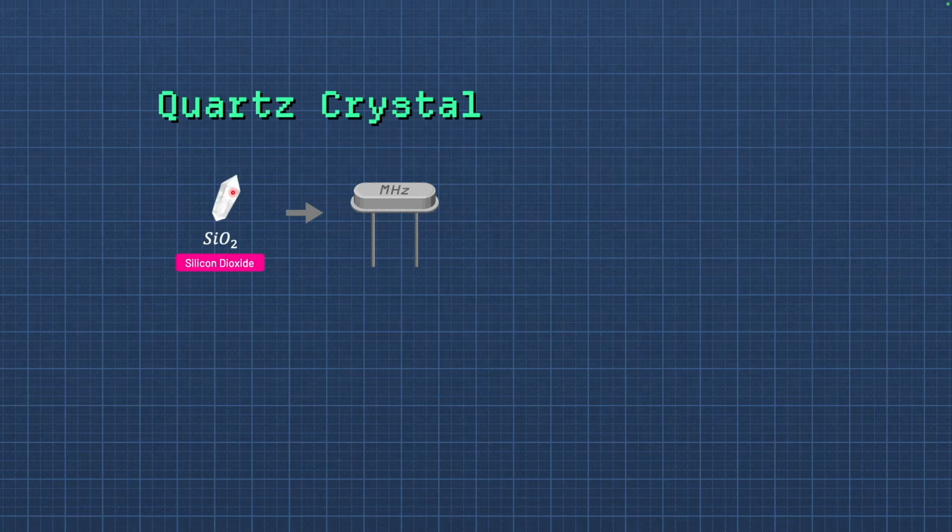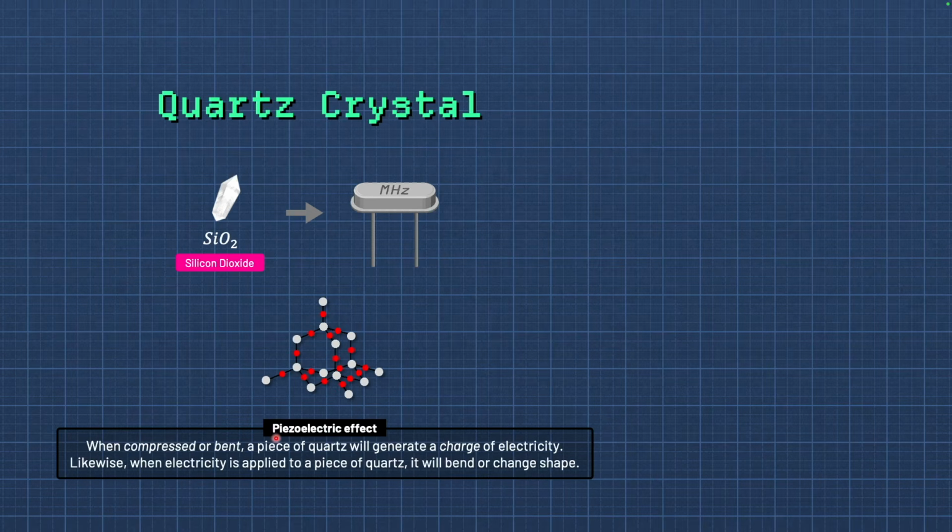And most of the time we will be happy with this explanation and move on, but you know us, right? We like to dig a little deeper into why things work. So the property that makes this vibration happen is a crystal property that we call the piezoelectric effect. This piezoelectric effect is a property of the molecular structure, the atomic unit structure of the silicon dioxide, where, let's just read what it says.